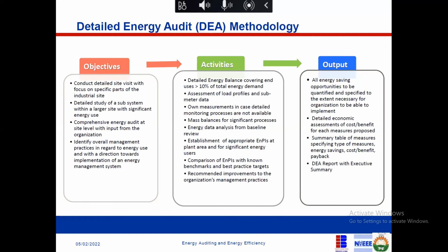And you must implement some level of monitoring processes. You put in energy meters, just like Yachipa said, you install these things, and you monitor them over time. The other slide talks about 7-day data logging. With the help of the clamp meter, you can clamp today, clamp tomorrow. After 3 days, you see uniformity, you can let go.